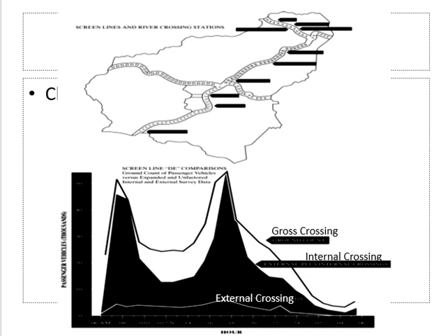Okay. Now let's say we want to do a count between Bahrain and Saudi. Now we cannot obviously do the whole Saudi. Let's say Bahrain and Khubal, right? This is the first city, right? We want to do a screen line count between Bahrain. Bahrain is one zone and Khubal is another zone. What is my screen line? The sea.